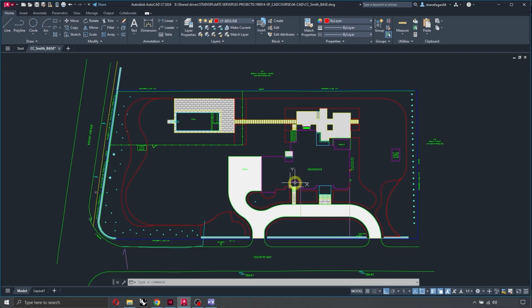Distance and area do not leave an existing object. If you use distance and draw a line, it's just there to calculate the distance. It's not leaving an object. Same with area. As we get into it, you'll see it gets covered up with a green or red overlay. That's not in your drawing. That is just a measurement tool to walk away with.